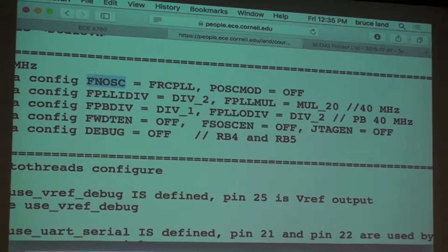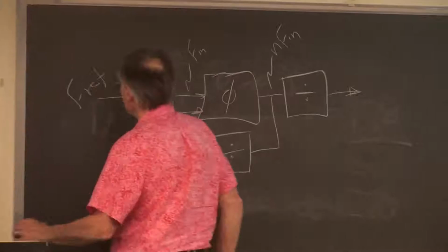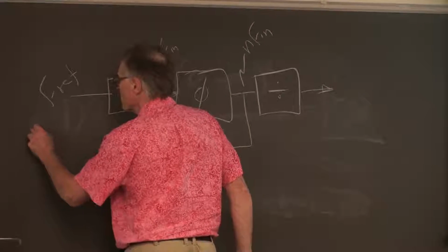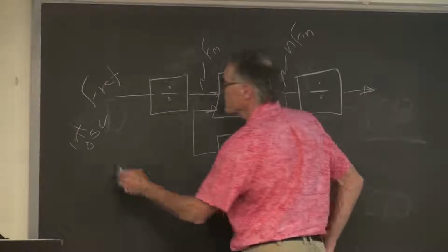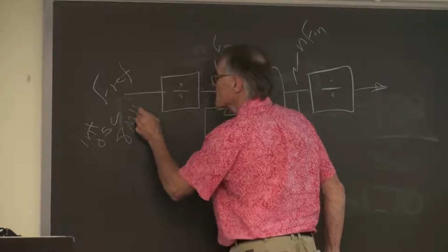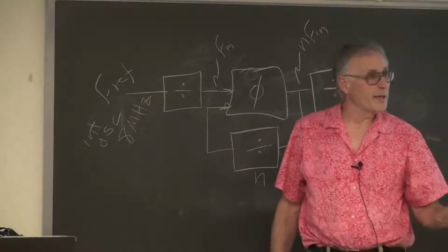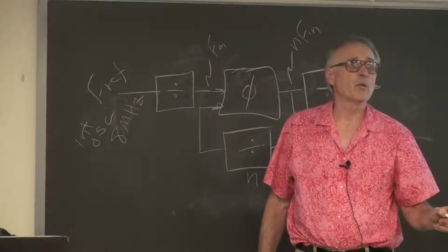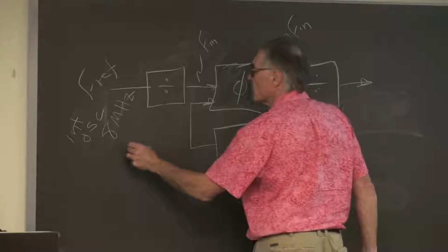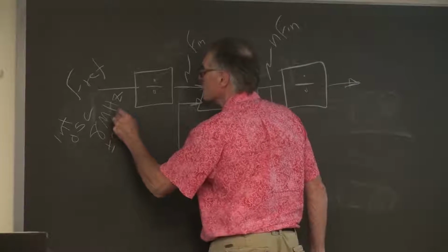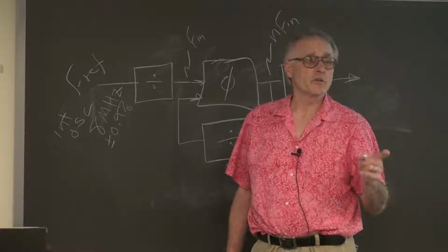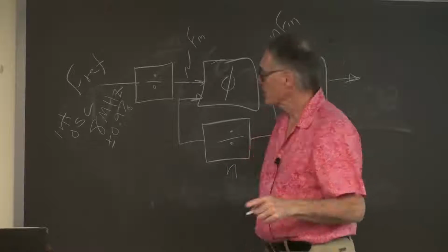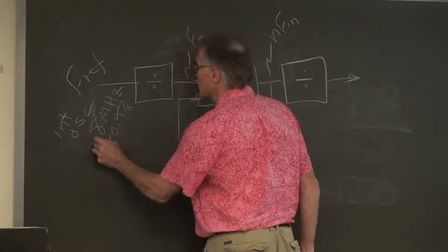So this is going to be the internal oscillator, which doesn't show in config.h, but this is set to 8 megahertz with what accuracy? You should all know by now. 0.9%. Plus or minus 0.9%. And you can trim that. You can make it exact if you care enough. You could trim that frequency using a trim register. But let's just call it 8 megahertz.